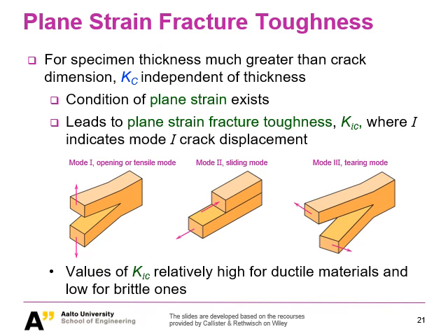So as you can see here, we have this opening or tensile mode. When we have a crack looking like that, we're trying to open it, and we want to see at what stage this crack will get propagated. This is one mode, we call it mode 1. And you can also see we have this so-called mode 2, so we have a small crack there, and we want to apply a slide mode. So basically you can see here it's shearing. So over there it's tensile load, and this is a shear load. And that will give you another value, unfortunately, another value of fracture toughness.